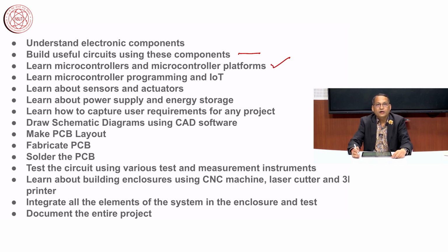Then we will learn about microcontroller programming and also IoT programming. We need to learn about sensors and actuators. Sensors will sense the physical environment, actuators will help us control the environment in some way. For example, you may have motors, you may have relays, you may have servo motors and things like that. Then no electronic system works without a suitable power supply. So, in this course you will be taught about various power supply topologies and energy storage systems, because many of these gadgets are battery driven.